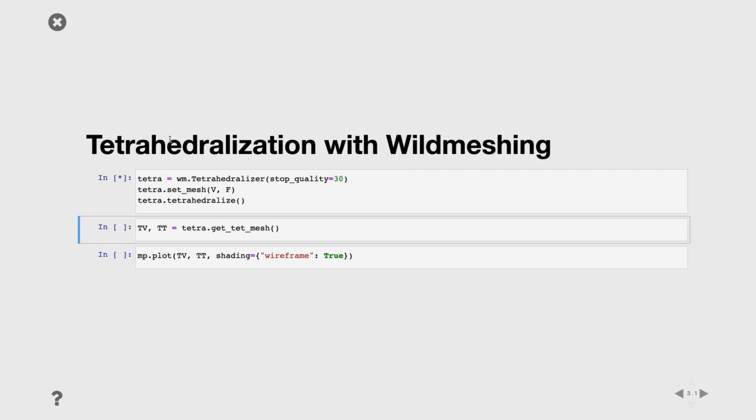So another thing here is that for timing reasons, I'm just stopping the quality of the tet mesh at maximum 30. Normally the default is 10, so here we are allowing for elements with a little bit worse shape. So I think it's almost finished. It also looks slower because I'm running on Chrome in full screen mode. It's usually a little bit faster. Okay, so it's almost finished.